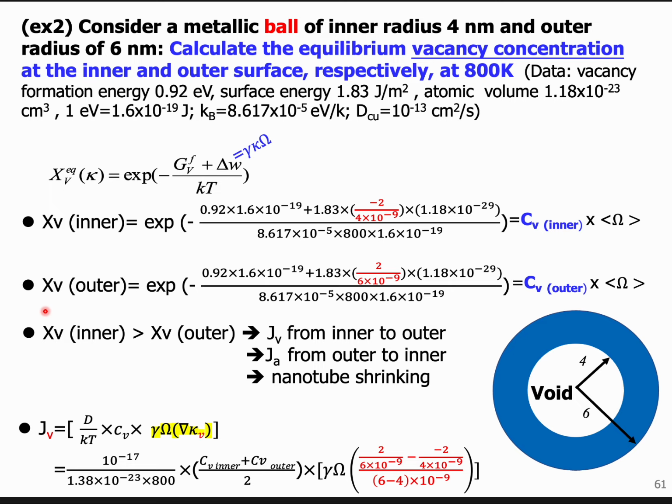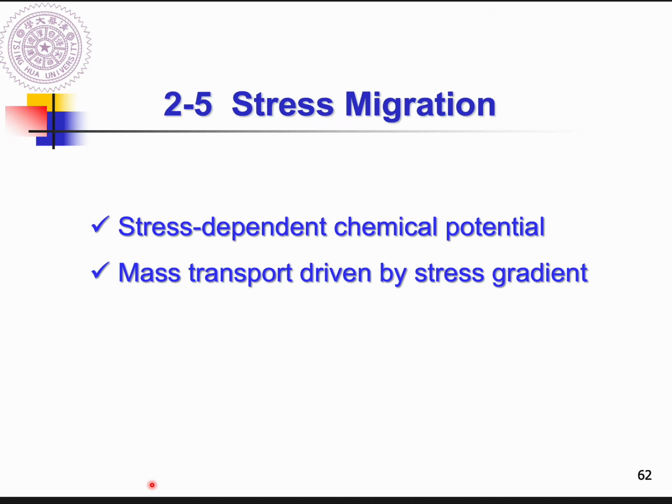You cannot directly use minus diffusivity times the vacancy concentration gradient to answer these questions. You need to use the driving force of the capillarity effect to answer these questions.